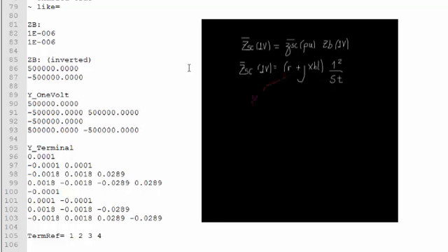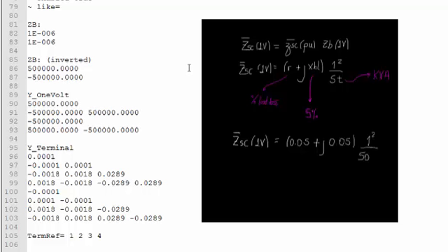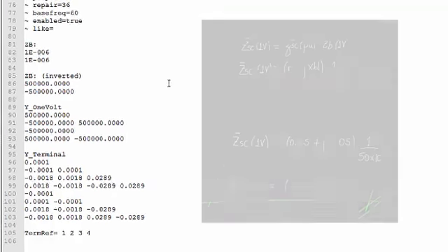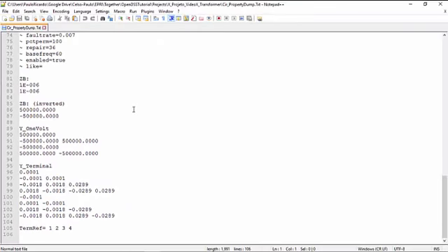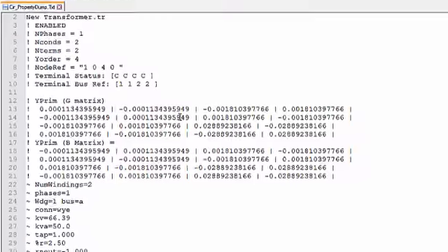R is equal to the load losses, that is 5%, and we also set XHL to 5%. Then, as the rated power of the transformer is 50 kVA, we have that ZB is equal to 0.05 plus j0.05 times 1. Remember that ZB is a 1 volt base over 50,000 VA. That is exactly equal to 1 plus j times 10 to the power of minus 6 ohm. At the end of the calculation process, this is the final Y primitive matrix.